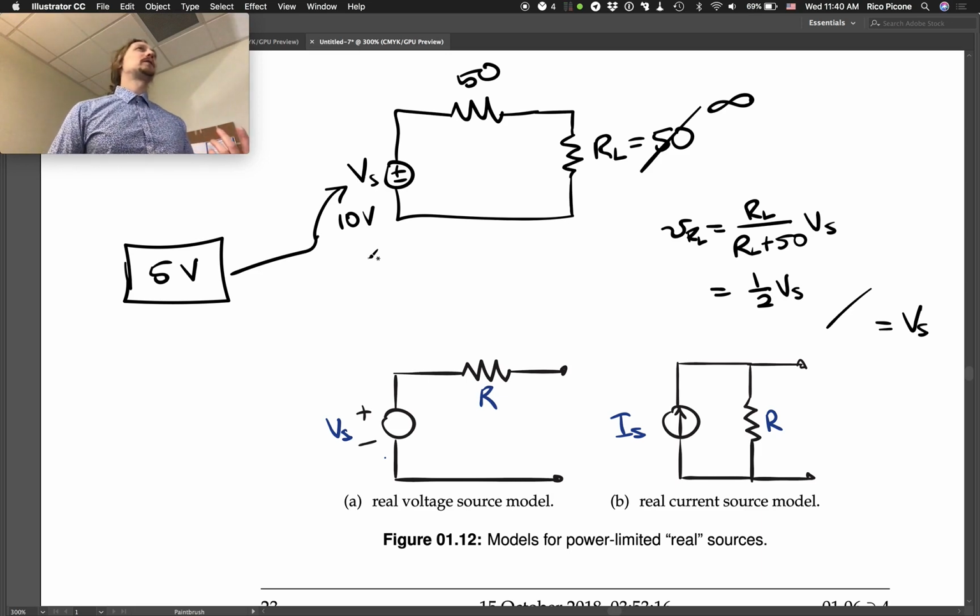The oscilloscope is smart, and it has a mode where it says, oh, do you have a 10x attenuator on here? If so, then go into this 10x mode, and every voltage that we measure, we're just going to multiply by 10 and read it out as 10 times. So the 10x attenuator is canceled out from the reading, which isn't really getting you anything. It just makes it look like you are able to measure higher voltages, but you have to have an attenuator, so there's no real gain in the amount of voltage you can measure. It's just a nice way of presenting it.